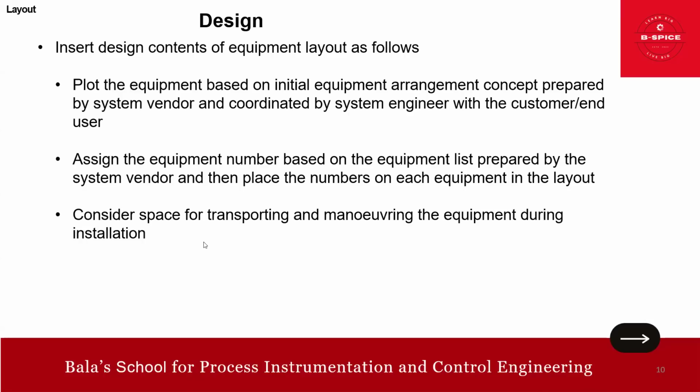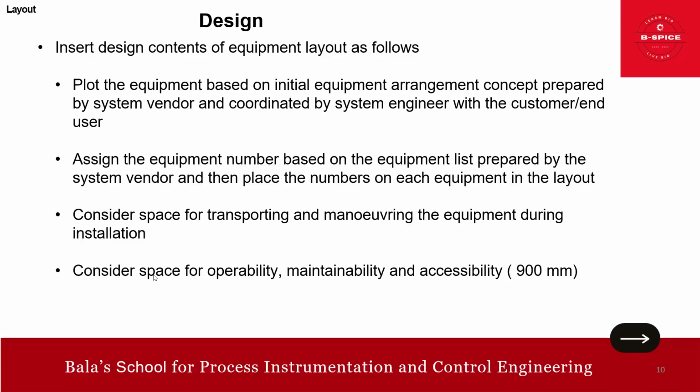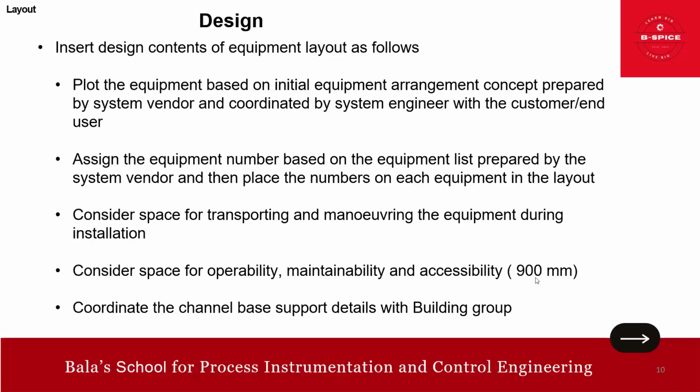Then consider space for transporting and maneuvering the equipment during installation. So there should be sufficient space for shifting all these. Then also consider space for operability, maintainability, and accessibility. See, approximately 900 mm. If you have sufficient space, you can go for 1 meter also.